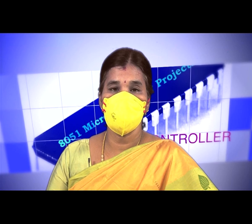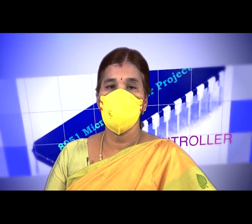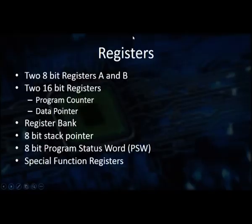So, generally in the 8051 we have two 8-bit registers, which are the A and B registers, right. It has a register bank. The register bank has 4 banks, denoted RB0, RB1, RB2 and RB3. Each bank has 8 registers, denoted R0, R1, R2 and so on, and these 8 registers are 8-bit registers.